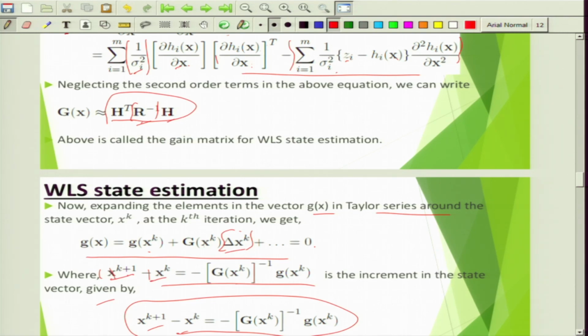Let us say 999 times out of 1000 it is giving a true value, then you will give it a very high weight. The measurement from that device is considered the most accurate. Let us say a specific measurement device gives the true value 500 times out of 1000, it is 50% weightage. So you are giving less weightage to that device. It depends upon the previous history.